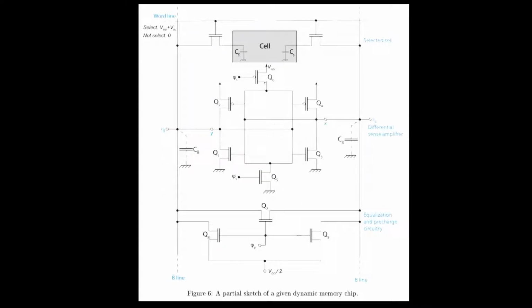So this is the dynamic memory chip that we're talking about, and in this question we're looking at the time-dependent behavior of the voltage at node X. This chip works in such a way that this capacitor stores a certain voltage, and to read out this value, this switch here is turned on, which means that this capacitor is connected in parallel effectively to this parasitic bit-line capacitance, CB, and as a result the voltage at node X will be a little bit higher or a little bit lower than some pre-charge voltage.